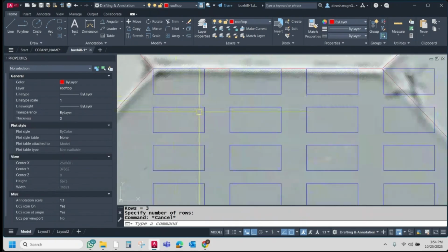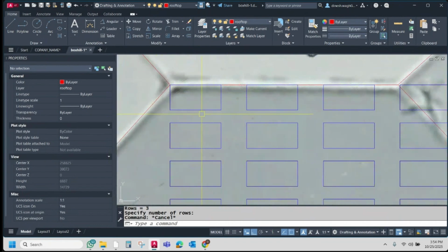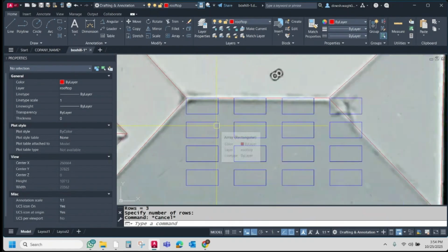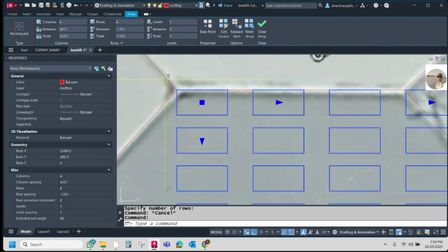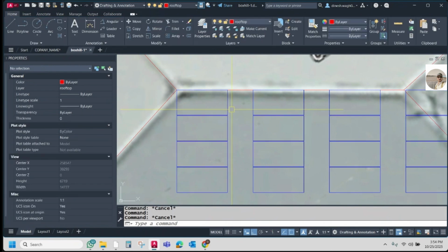So what we will do, first we will check the dimensions of the module. If we remember that, then it will be good. If we don't remember, then we simply measure and then put values. So for this width, it is 1134. So I am just directly going to put here the distance between this part will be 20 mm. So here I am going to put minus 1154. So now you can check here, it is a 20 mm gap.